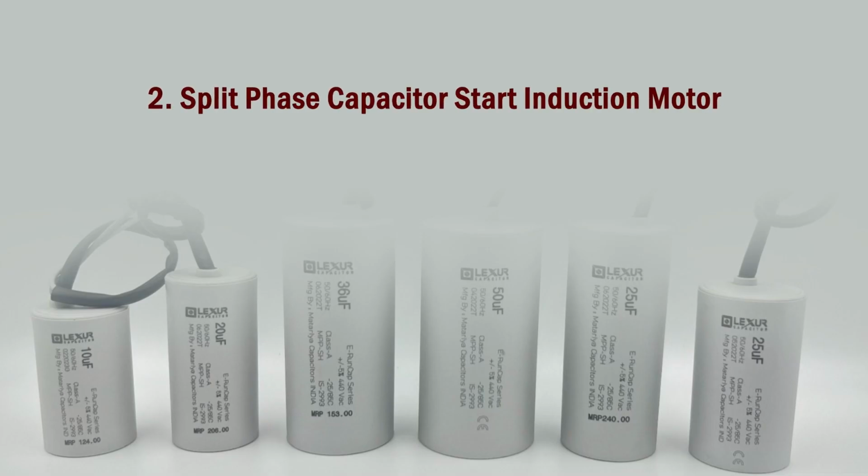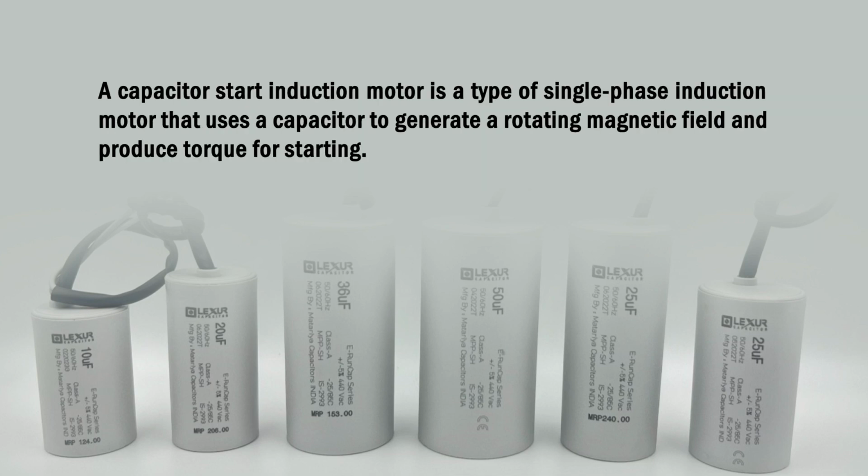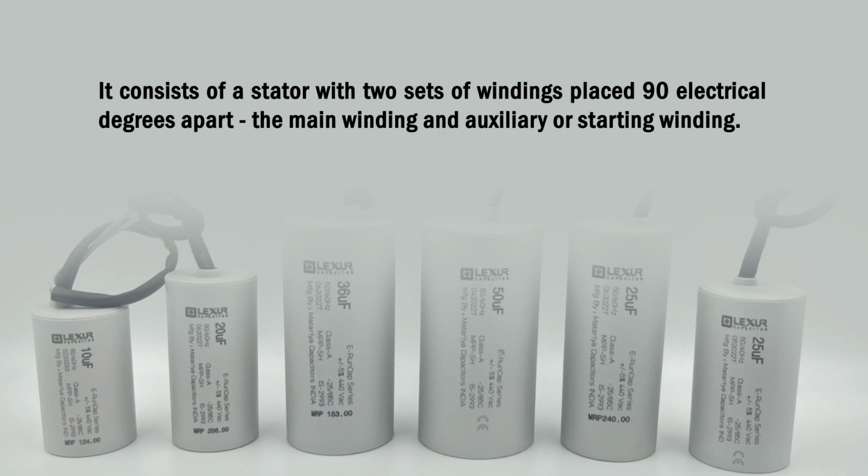Next is the split phase capacitor start induction motor. A capacitor start induction motor is a type of single-phase induction motor that uses a capacitor to generate a rotating magnetic field and produce torque for starting. It consists of a stator with two sets of windings placed 90 electrical degrees apart, the main winding and auxiliary or starting winding.